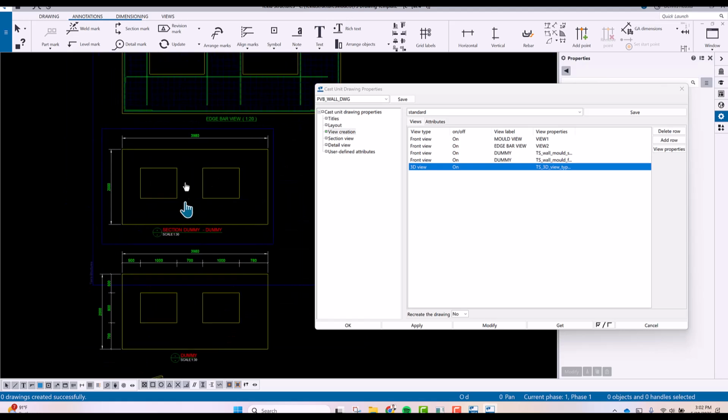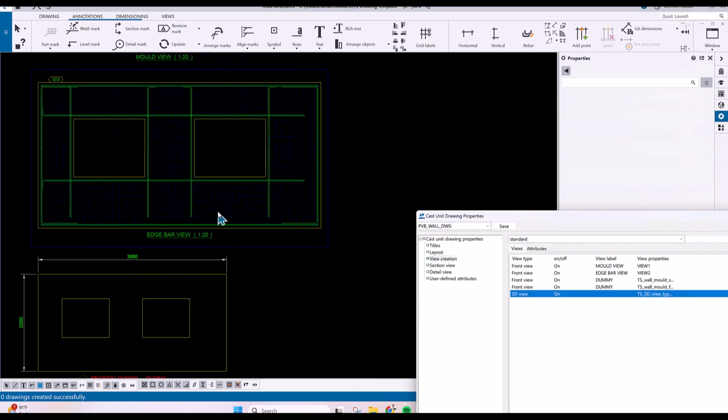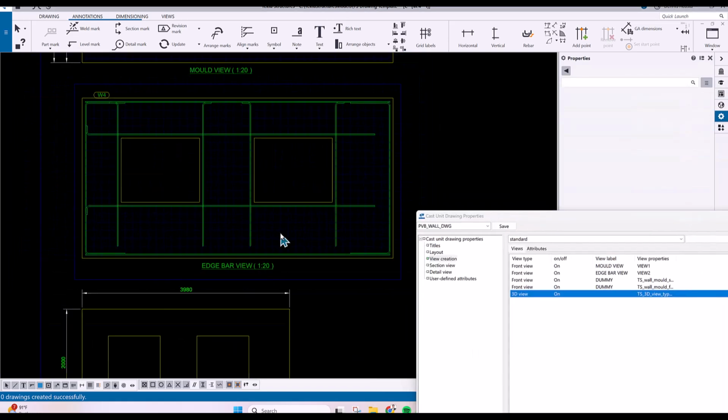But again, the one that I want to specify to you is this layering. This one is very important for you, because if not, then you have to delete, hide, so no need. If you have a proper naming convention, okay, I want to show only this layer 1, layer 2, layer 3, so just set it up, and then you will get it automatically.